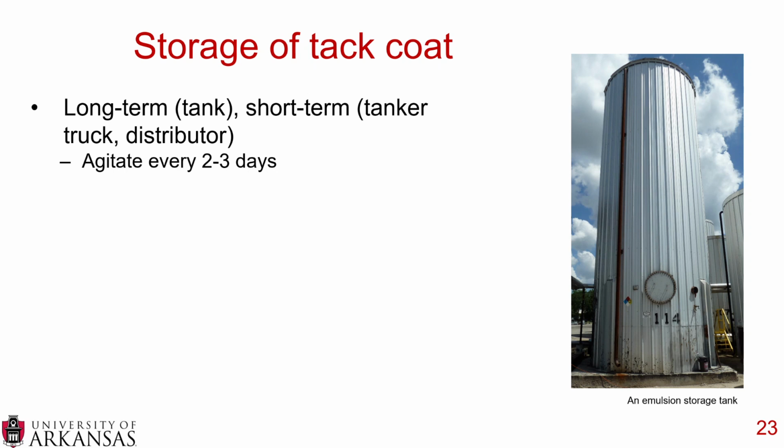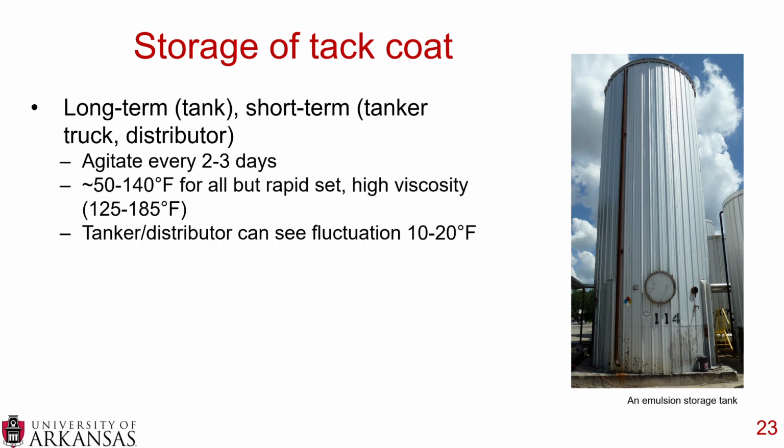You do need to agitate your tack coat material every 2 to 3 days. You want it stored at about 50 to 140 degrees Fahrenheit for all but rapid set and high viscosity. And for rapid set and high viscosity, you want it a little warmer, at 125 to 185 degrees Fahrenheit.